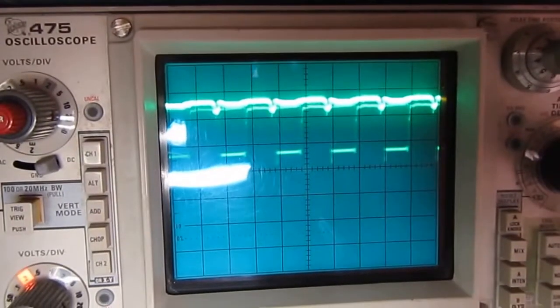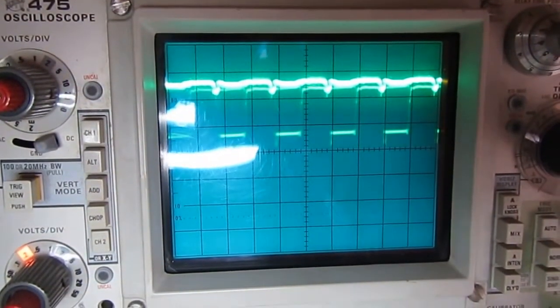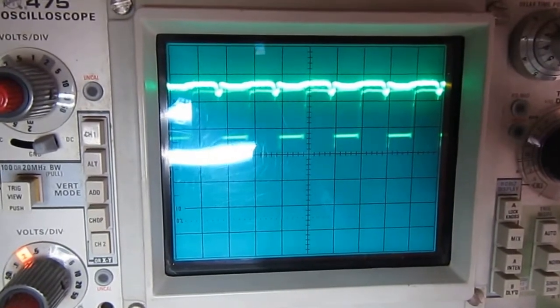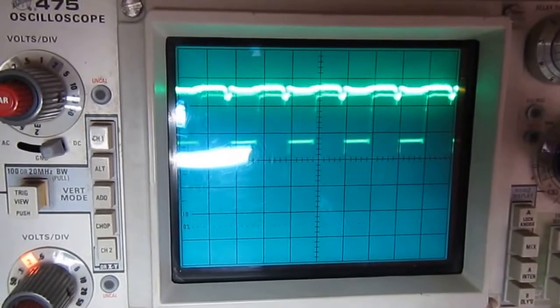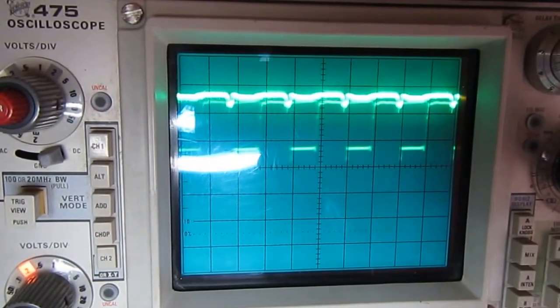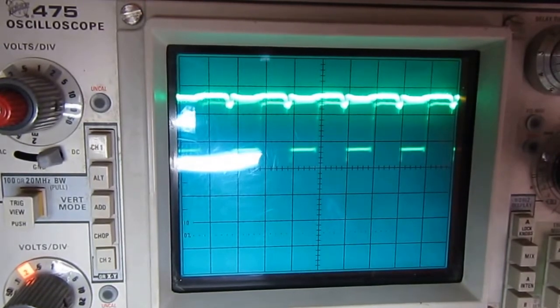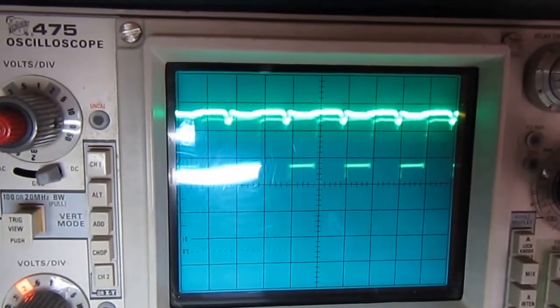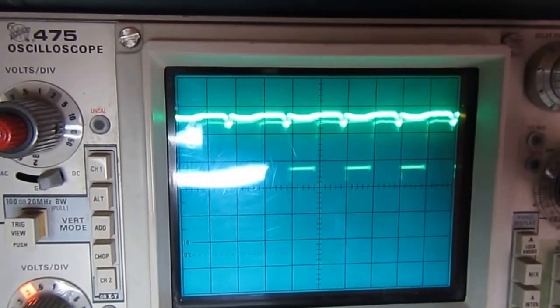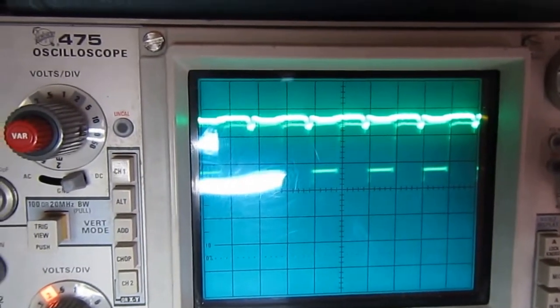This is the 7, and you see a good signal also here. That's probably because the current for this pin was shared with the current for the other pin, and removing the short on that pin cleaned the signal also on this pin.